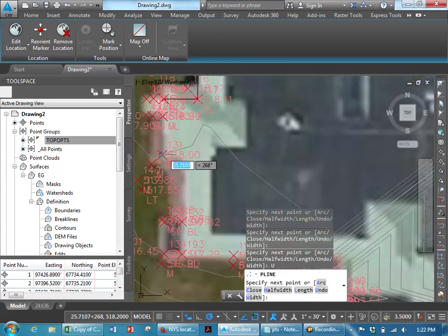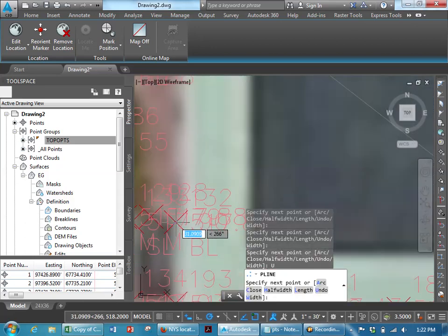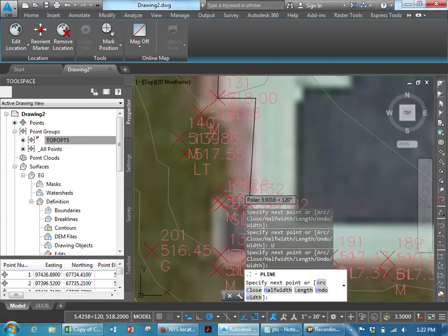Typically, for this one they couldn't see into this corner, so what you would do is take 90 degrees off of this angle, 90 degrees off of this other line, and you're going to be pretty close. I'm just doing this roughly to give you an idea of what it needs to look like. Obviously that's not a 90-degree corner. You can use the rotate command to actually rotate a line 90 degrees. So for example, let's do that.